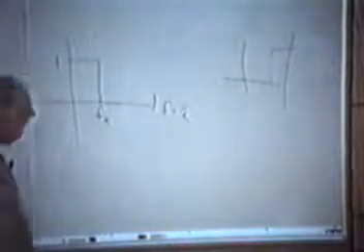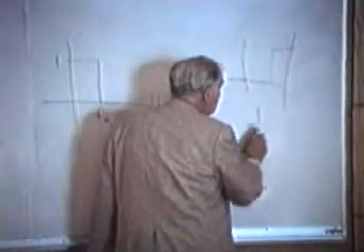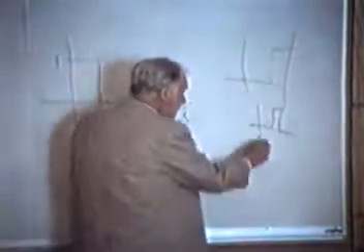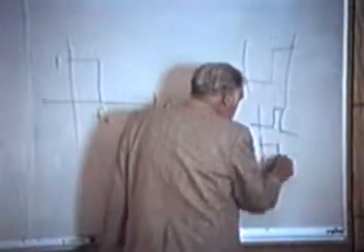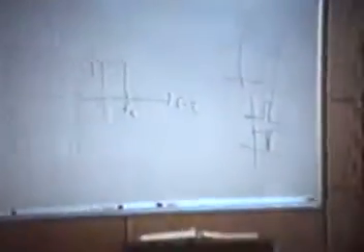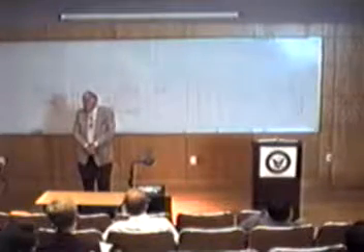I might want a band pass, or a band stop, or a notch filter. A notch filter is one that takes out one frequency. You want that frequently because in the laboratory, 60 cycles is everywhere in this country. In England, it's 50 cycles. And it's everywhere. So you want frequently to build a filter which takes out 60 cycles, removes it.